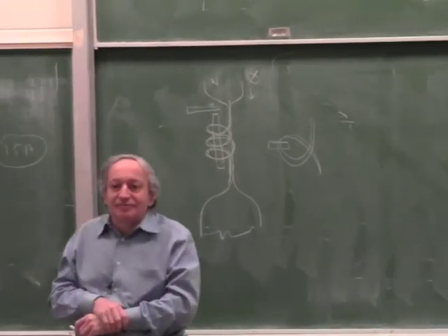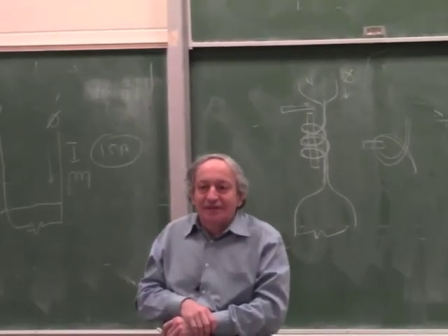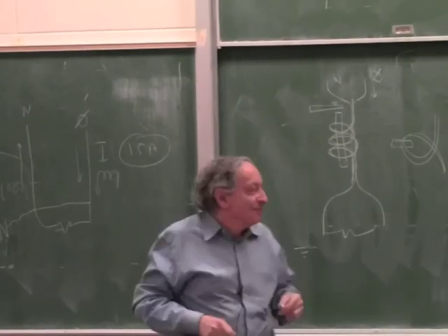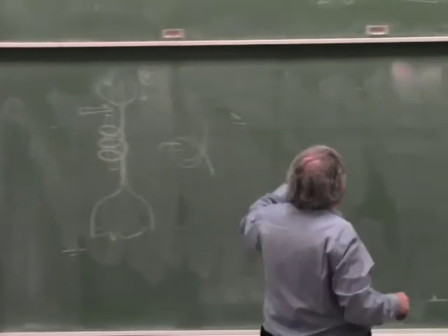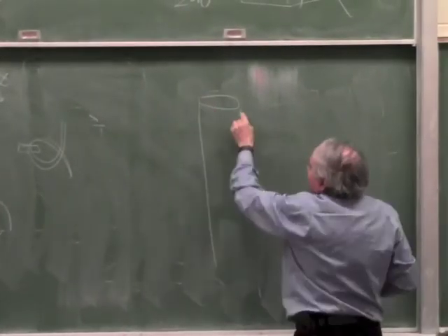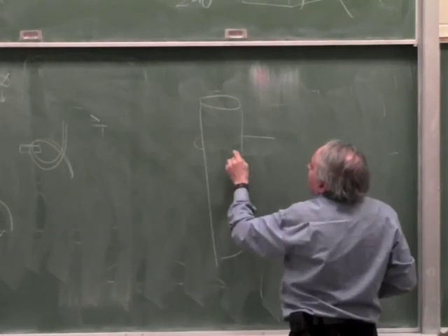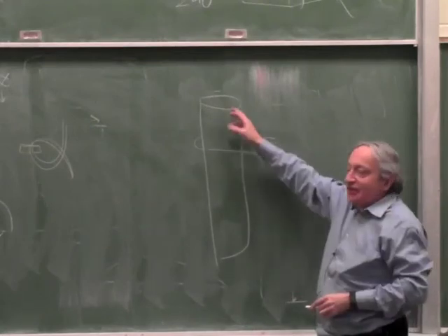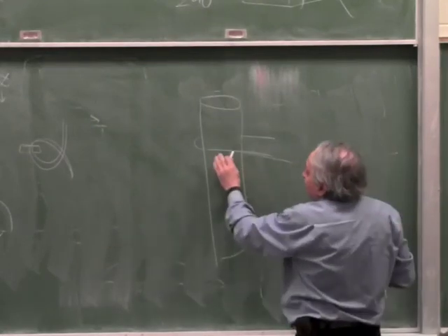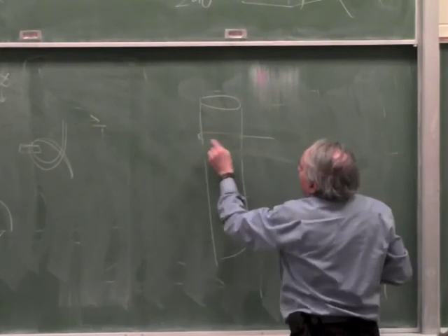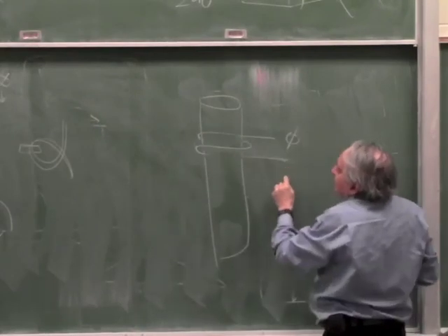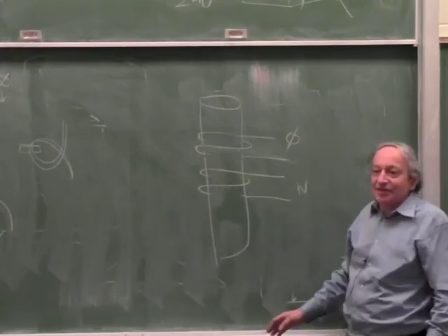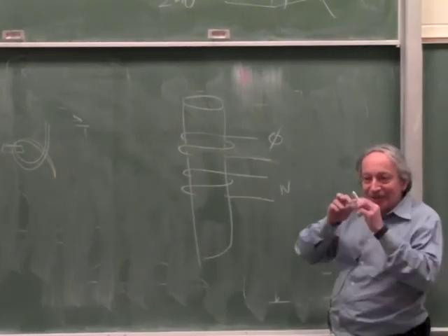If you put the two wires next to each other, they're still different because of the distances between them. True, but luckily when you wind it, it doesn't matter, like I explained with the LVDT, because in electromagnets, it doesn't really matter where you put the turn, it wouldn't change the magnetic field. You can move it back and forth. So even if you had on the same rod two separate windings, it'll still work. If you have one winding for the phase, and a completely separate winding for the neutral, as long as it's on one flux path, it will still cancel out. So it's not important if the wires are really close or not.